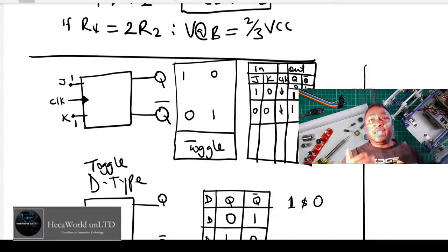And we built a fail-safe or security feature there, that when you get the combination wrong, it will reset your flip-flops. So when you hear me talk about set and reset, you use the reset. Say, when I get this wrong at this stage, go reset everything so I can start over. And you can use a count to say, when I do this 3 times, block it for a certain amount of time. In that case, we use 555 timers to create a delay.